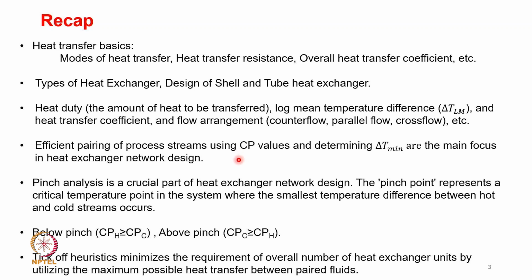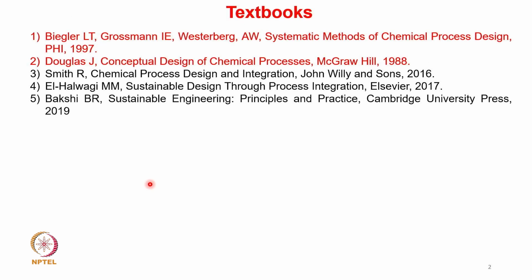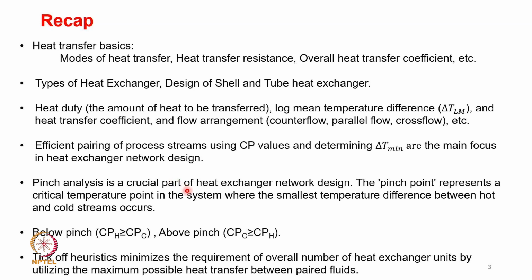Further to that, we went ahead and looked at pinch analysis, of course a crucial part of heat exchanger network design. The pinch point represents a critical temperature point in the system where the smallest temperature difference between hot and cold streams occurs. So controlling the pinch point is an essential thing in the design of heat exchangers.